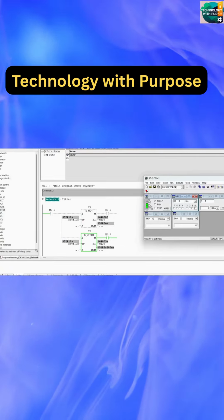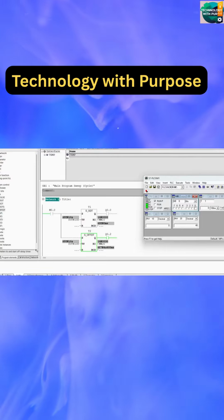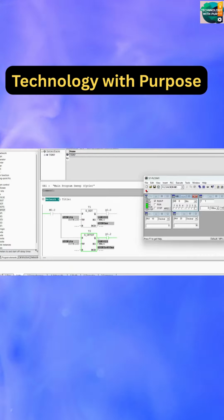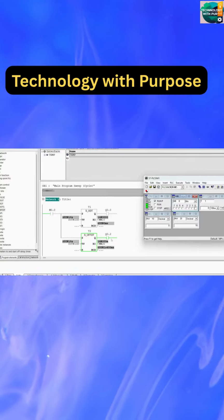You can see that once M0.0 is off, immediately the counting of T2 started. But if you observe, the moment M0.0 was turned on, the output of T2 was also on. Which means in the off delay timer, once the input is on, at the same time the output is also on. Now you can see that after M0.0 is off, T2 started its counting, and after counting is